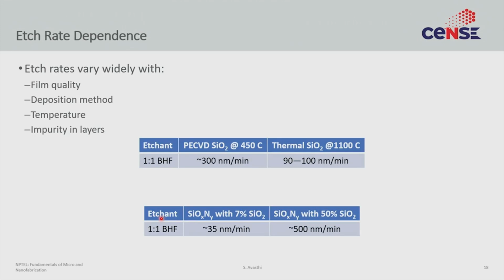However, in wet etching, a common feature is that the etch rates can often vary wildly. No matter how well known a recipe, HF, H3PO4 are fairly well known etches, but even then, different labs get slightly different numbers. And the reason for that is that different labs etch films of different quality.